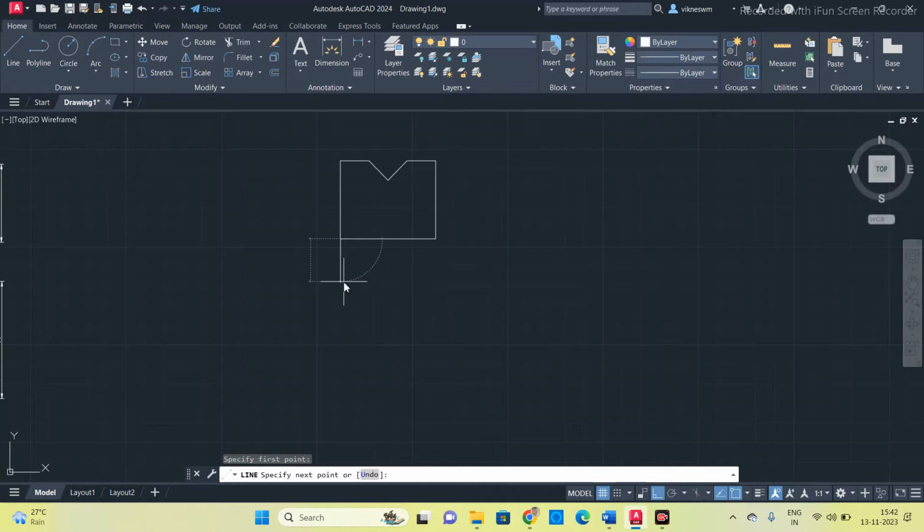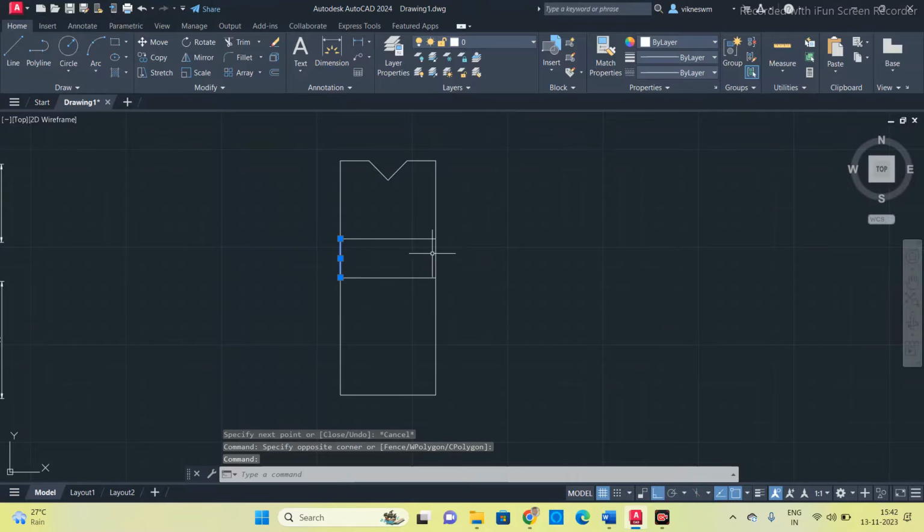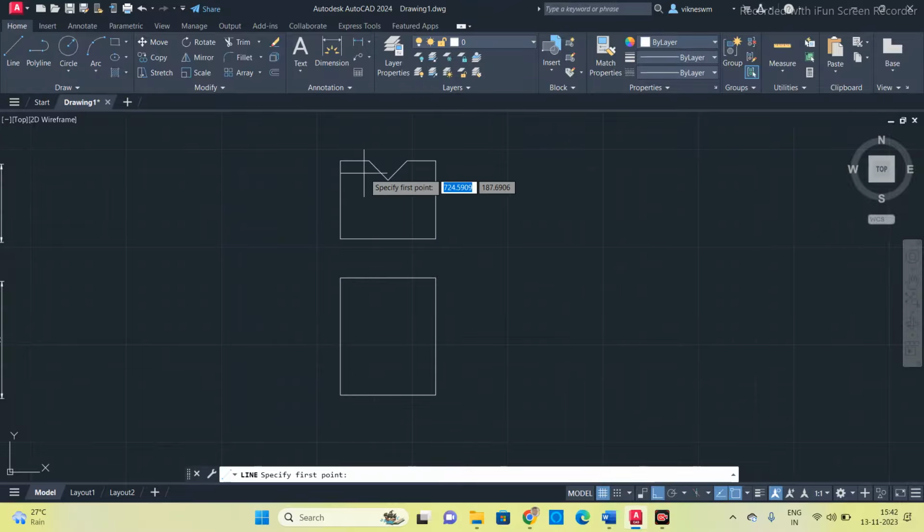Next we will draw the top view. First put the reference line. So this length is not going to change when you see from the top. This length is 60 mm, again 50, then close. Delete these two lines. So again take the line.